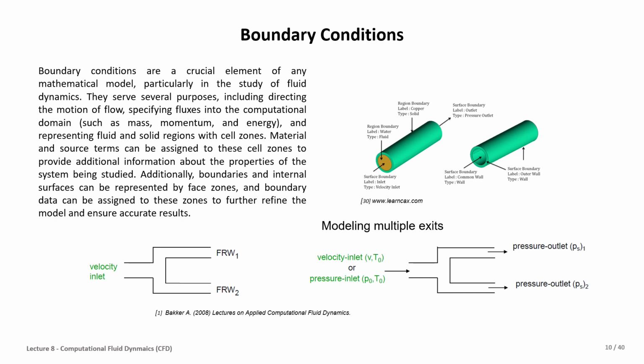But when we look at the next one on the left hand side, it has an inlet, a velocity inlet. So this is different, we need to use a different boundary condition, because we will have the outlet from the pressure for this one, but for the one without an inlet we don't need the outlet. For the multiple exit case also, you see this example here.